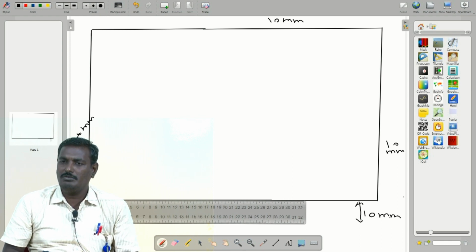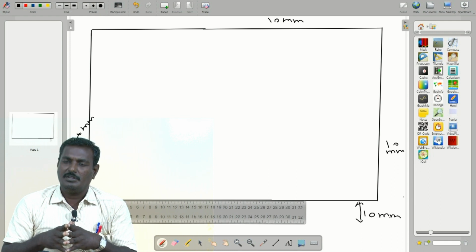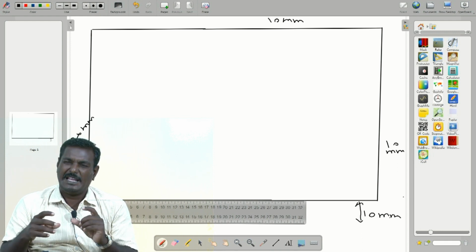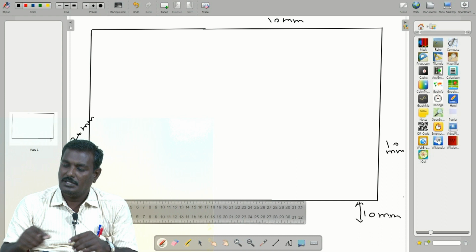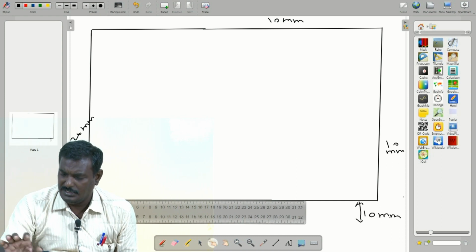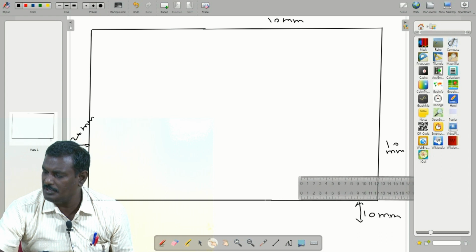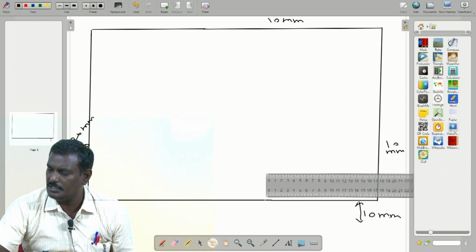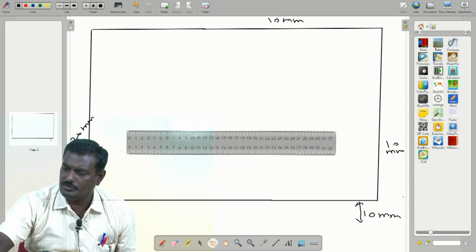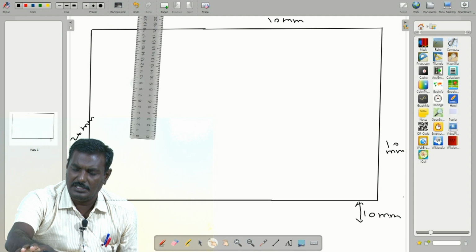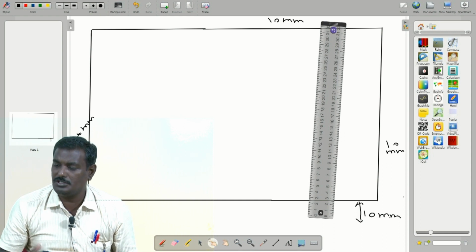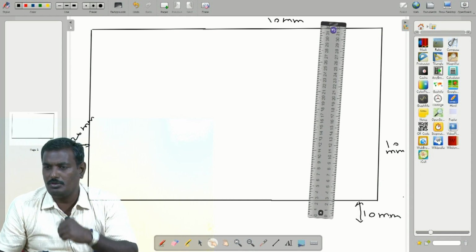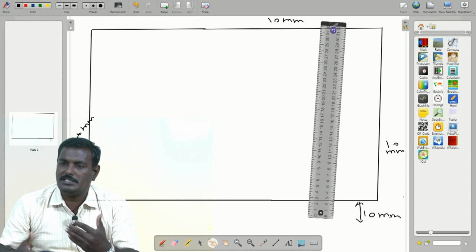Next you have to give your details, but probably in our sessions we are using 100 mm length and 90 mm height. It depends upon the use of details in that column, that is called the name block. Here again I choose a scale for 100 mm, that is 10 centimeters. 10 centimeters I want to draw, but the height is 90, so I want to choose the height first. For this difficulty you have to use a mini drafter scale, because the two scales are perpendicular to each other, but in this package of open board, we are not able to get a mini drafter. So I just use only scales.